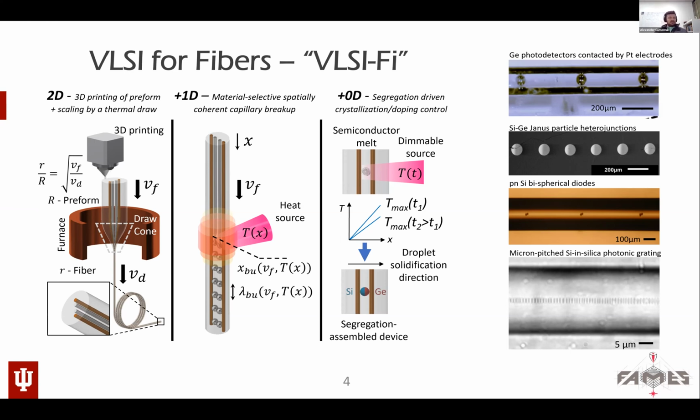We fill it with active materials, for instance, metals and insulators in that case, at the geometry arrangement that we want in the final device. Okay, then we take this thick and short rod, dip it into the tube furnace, heat it up to a state of a viscous liquid until it glows white and drops down, carrying with it a thin strand of a fiber. We grab on that strand of a fiber and draw it very fast on the bottom.